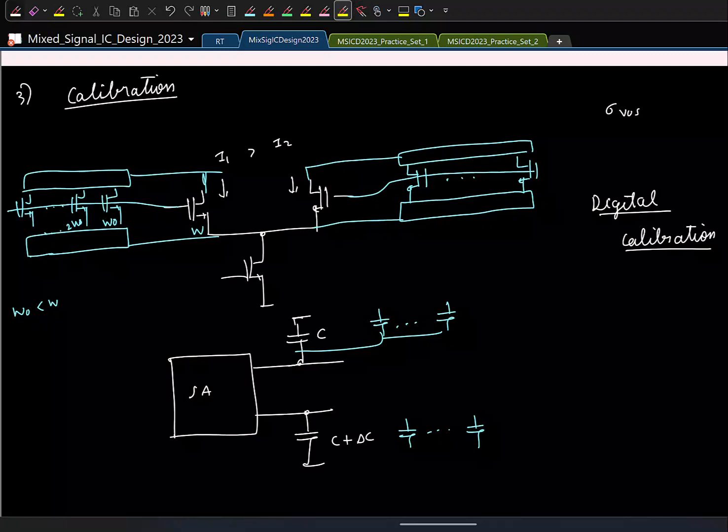It's simply a matter of the controls for these switches, right? It's essentially digital logic. Here, anyway, it's a comparator. Outputs are digital. You look at the digital output, have some logic that finds if you have mismatch or not. If you have mismatch, you turn on switches here that will put transistors in parallel and see if it's correct. Is that okay?